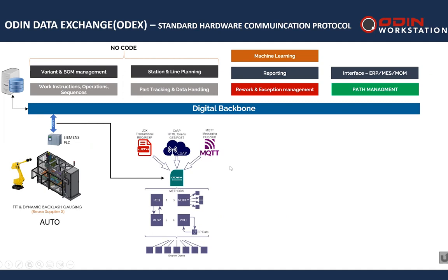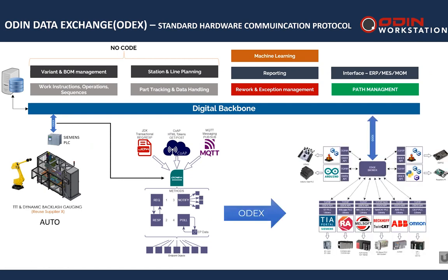We've studied a number of existing protocols, MQTT, CoAP, and ultimately we've taken the best of all worlds, the request-response concept, the notify concept, the poll concept, and built that into our own communication protocol called ODEX. That enables us to create libraries, and we've already created the library for Siemens and Rockwell.